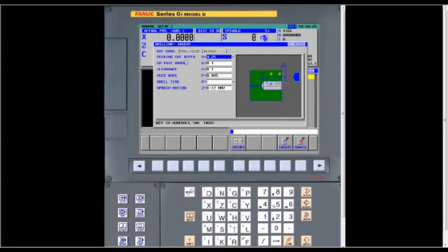So it's asking for pecking cut depth, and you can see it has Q highlighted. That's like if you're doing a G83 drill cycle where you want the drill to fully retract; that's the amount of each peck. Then the go past amount is just to allow for the angle on the drill. The clearance is like an R plane at the start of a drill cycle. Then your feed rate and dwell time, which again has an asterisk. You do not have to answer that, but that's like dwell time at the bottom of the hole. If you wanted it to dwell for part of a second, you could put that in.